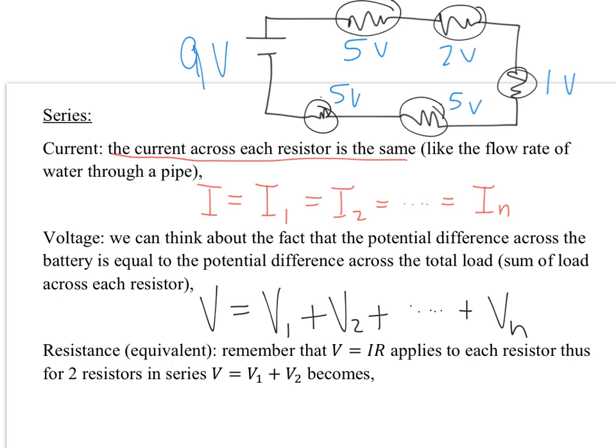Because remember, what's the formula for power? Power, P equals what? You know, electrical circuits, not work over time. Power equals what? V squared over R is one of them. What else though? I don't want to use that one for now. IV is the simplest one. And take a look. I, for each of these bulbs, are the same. They're all the same I values, but V is different, isn't it? So if a bulb has a different resistance than another bulb, not only is the voltage different for that bulb, but the power is going to be different as well. This idea is going to continue in your lab, okay, with power.